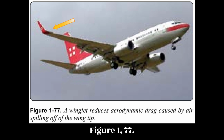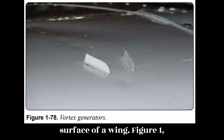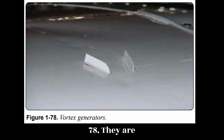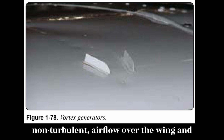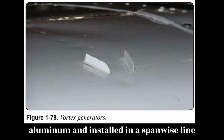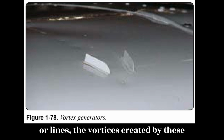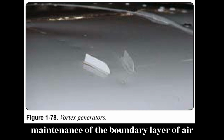Figure 1.77. Vortex generators are small airfoil sections usually attached to the upper surface of a wing. Figure 1.78. They are designed to promote smooth, or non-turbulent, airflow over the wing and control surfaces. Usually made of aluminum and installed in a spanwise line or lines, the vortices created by these devices swirl downward, assisting maintenance of the boundary layer of air flowing over the wing.